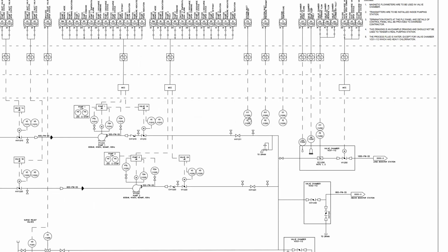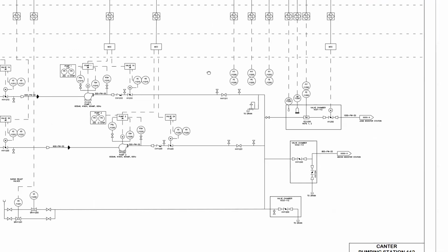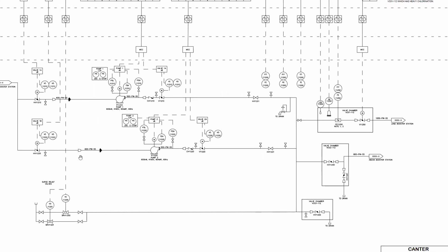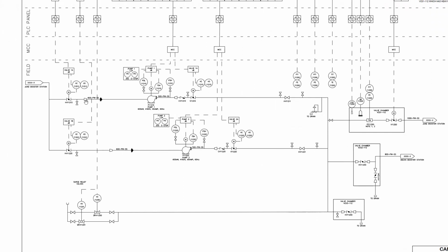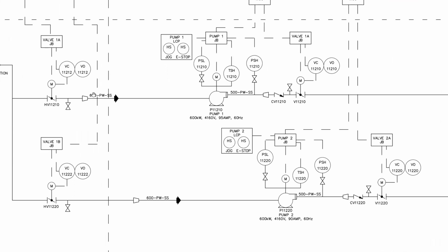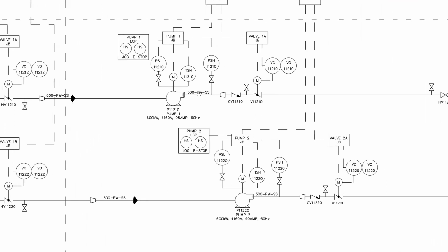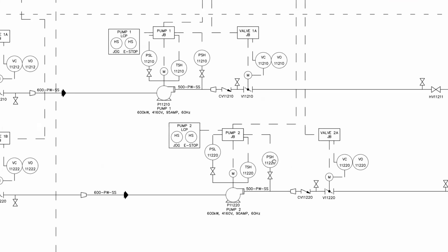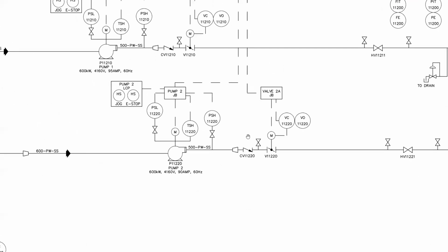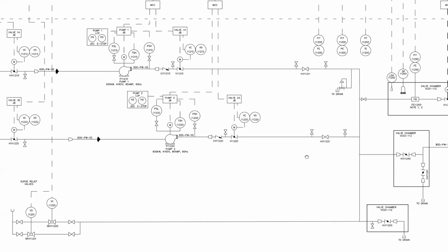So we have here a flow meter. One of the things I don't love about this is it's not showing where the flow meter is. So we see we've got pumps, we've got reducers here. So we have a line coming in and a connection, 600 millimeters flow in this direction, 500 millimeters. So we do have a change in pipe diameter and then potentially another change in pipe diameter, but it doesn't indicate what it is.